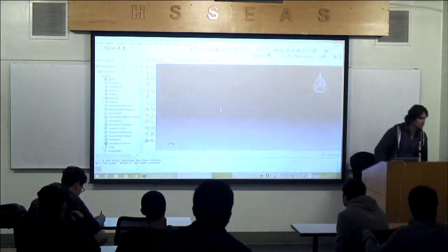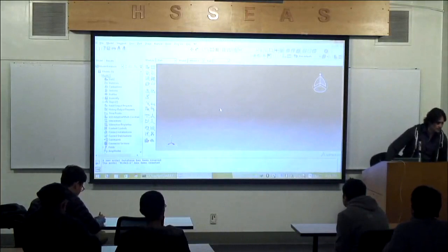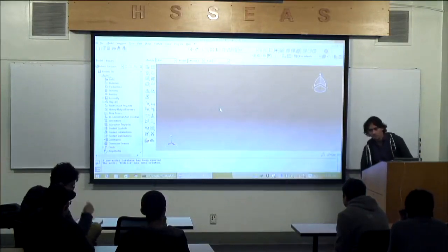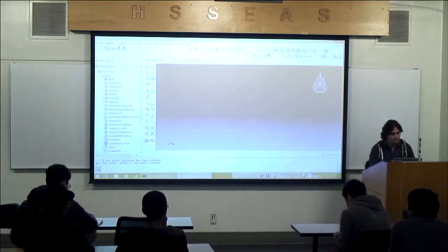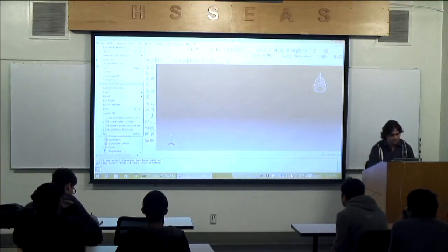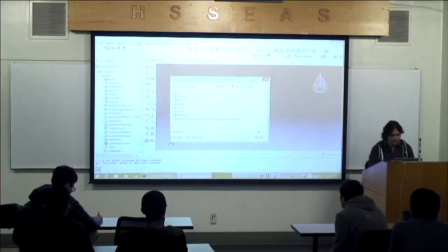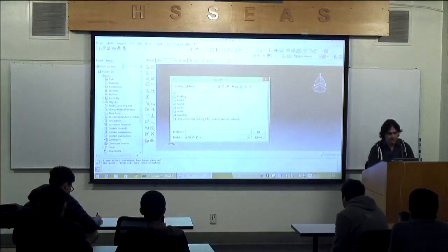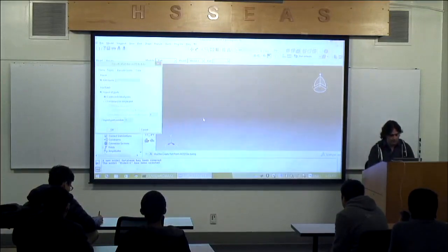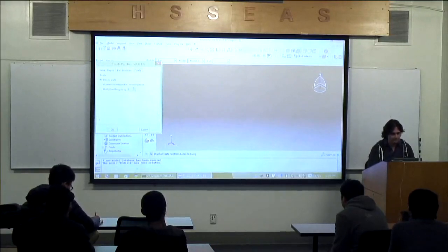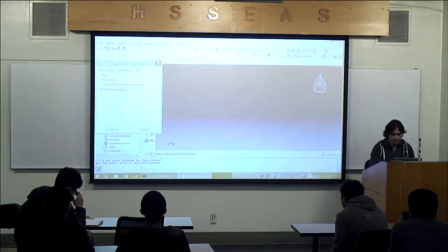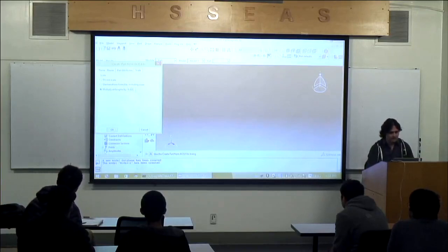All right. So to conduct the extraction of the frequencies from a model, we're going to import this model from any CAD. So we go to the menu bar, to import, to part. Once we go to part, we need to find the file and click to import it. In this case, the file is in millimeters, so we're going to multiply by some scale to make it in meters. So let's apply the scale.